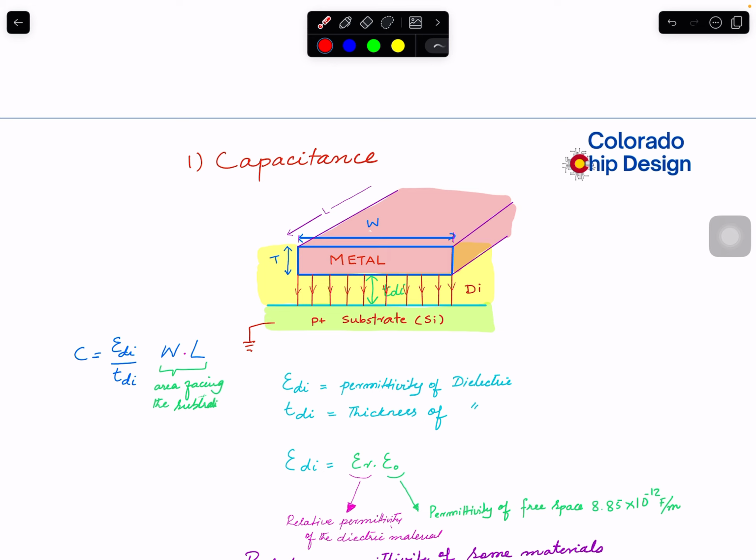Now let's assume it's silicon dioxide. Not only between gate and the channel, but dielectric is all over the place. Wherever there is no metal, there is a dielectric. It's called interlayer dielectric. And in this case, I'm just making an assumption there's a metal going over the substrate region. Maybe there's a metal one, there is no transistor underneath, and it sees a substrate connection. In this case, you can see the height is smaller compared to the width.